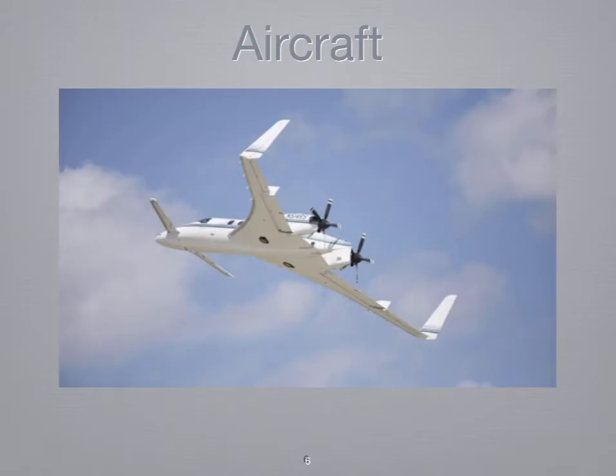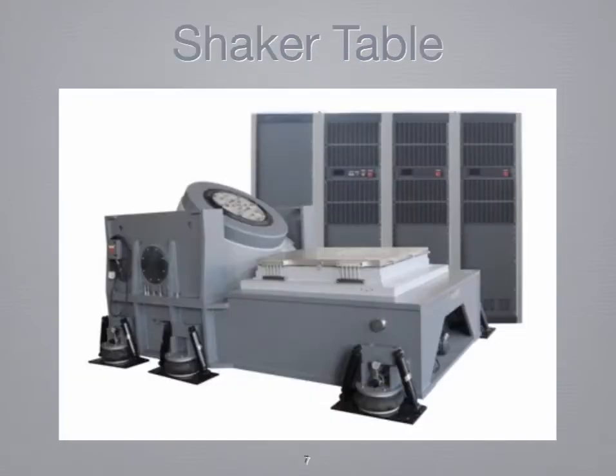Also in aircraft, in the 1940s, many new aircraft were needed for World War II. And so the development of increasingly complex instruments and higher airspeeds drove the need to test instruments before flight certification. And the way that's done is using things called a shaker table. They are used to model vibrations and are designed for testing electronic or mechanical components.